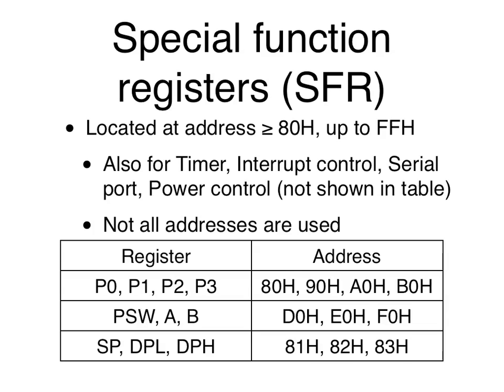So they've defined the ports, general purpose I/O ports, which will be the topic of this week after I go over this. P0, P1, P2, P3, these are the general purpose I/O pins. There's the PSW, which we've seen. A, really, that's the ACC, right, accumulator. B, another accumulator-like register. So those have the addresses D0, E0, F0. So anything that ends with a 0 or an 8 in the special function register space is also bit addressable, as you probably recall last time.